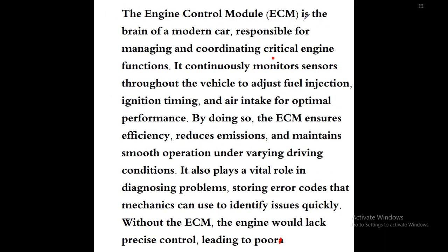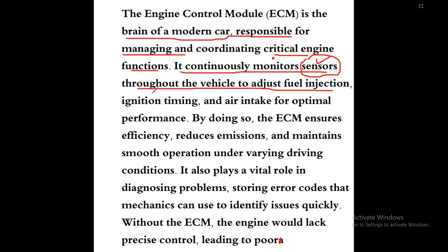So the engine control module is the brain of a modern car, responsible for managing and coordinating critical engine functions. It continuously monitors sensors throughout the vehicle to adjust fuel injection, ignition timing, and air intake for optimal performance.